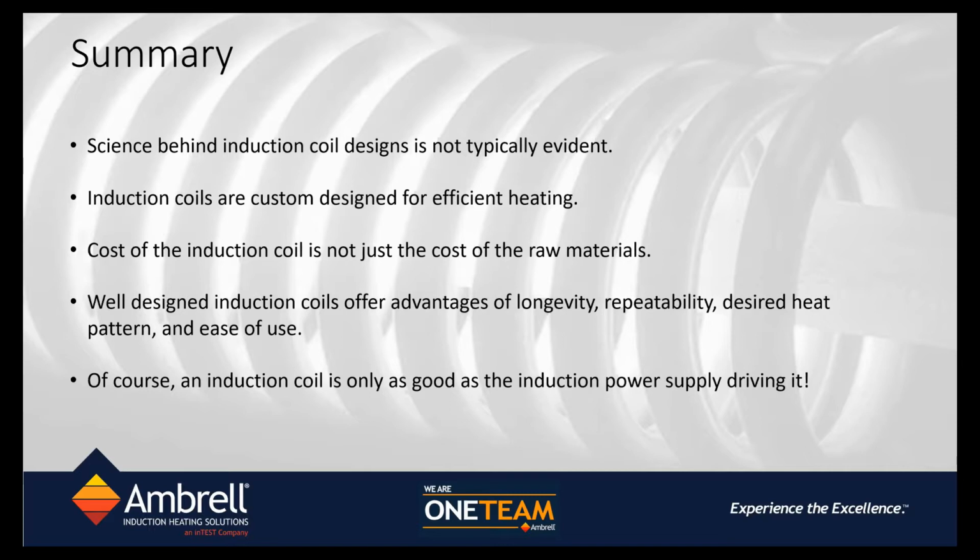And finally, the induction heating coil is only as good as the induction heating power supply driving it. You could have the best possible coil design, but if the induction heating power supply is not up to par, then you may not be getting the benefit of the automatic frequency tuning and automatic load matching that is available in today's induction heating power supplies. So with this, I'd like to conclude our presentation today, and we'll open up for some questions.